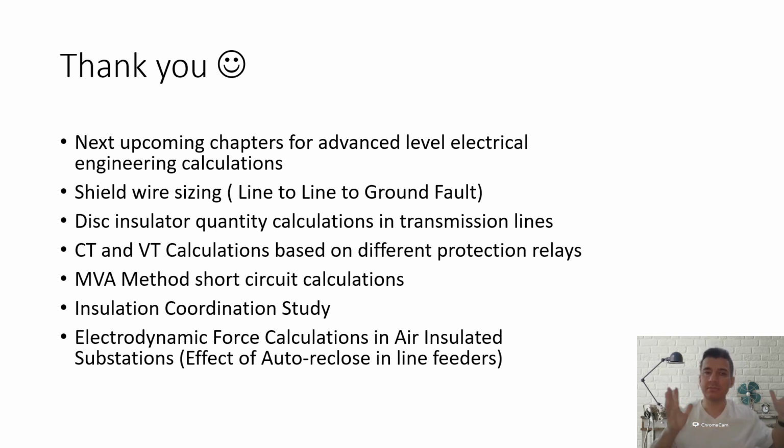What is the maximum allowable length of one tubular bus bar, considering its diameter, its length, and the short circuit level, because there will be a frequency, and how will we damp that frequency? Why are we putting inside of it one or two additional conductors, not pheasant, maybe the other one, cardinal conductors, just to damp that natural frequency?